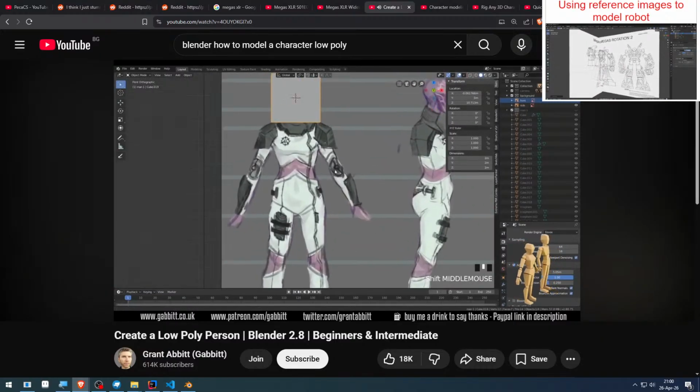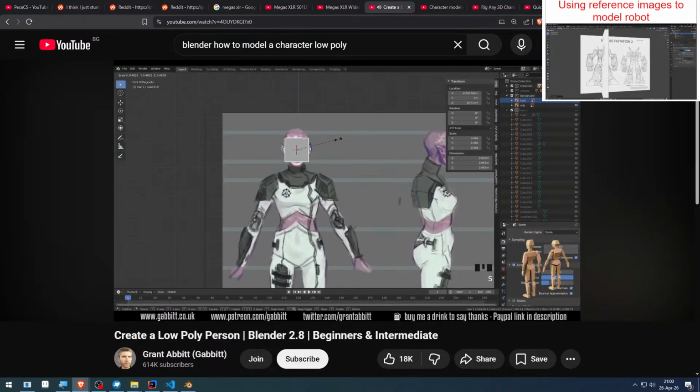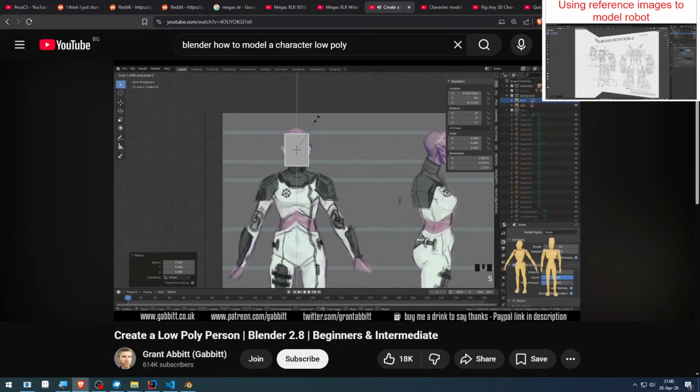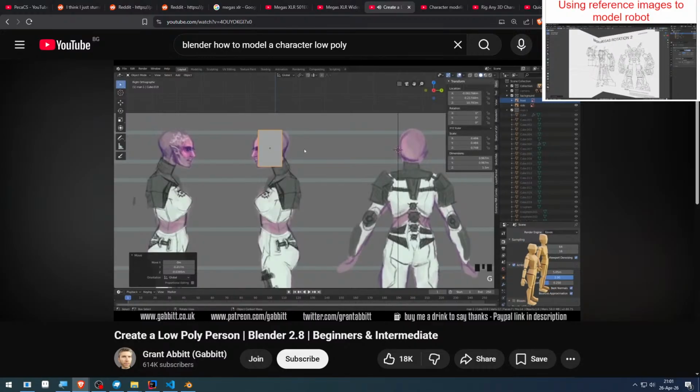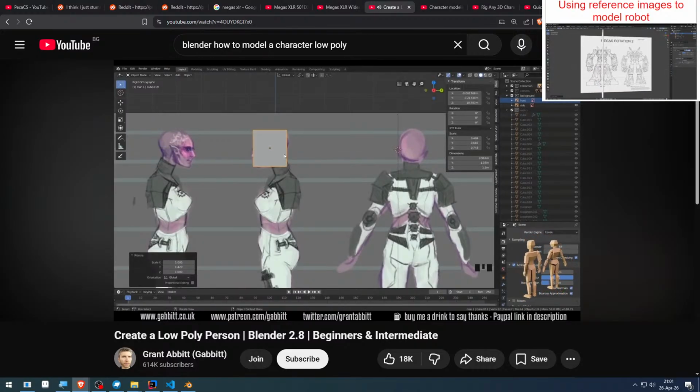So I can go in and start reshaping. So let's scale this so it's the right size in the x-axis, scale it so it's the right size in the Z, and just move it into position with G. And now I need to adapt this shape really slightly. Let's go to side view, move it into position, and scale it in the Y. So it's roughly the right shape.